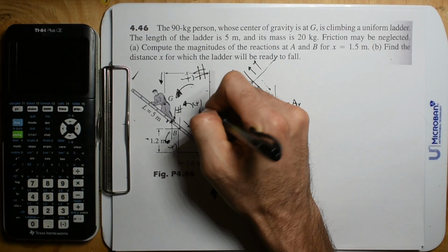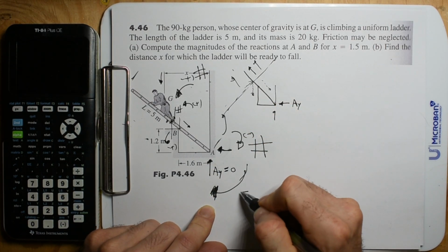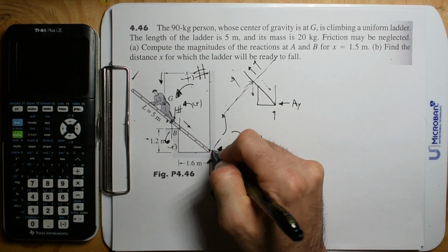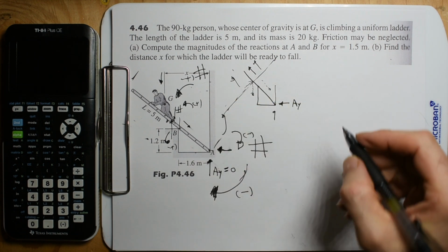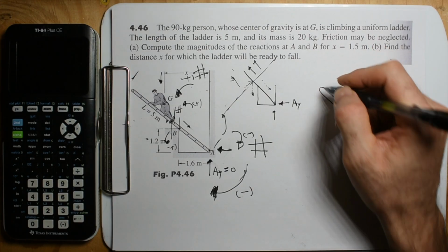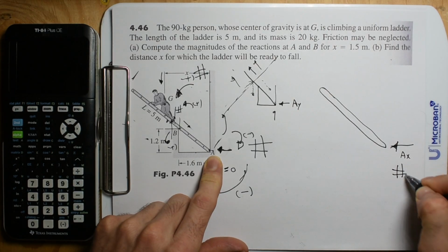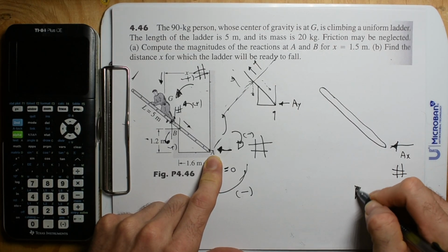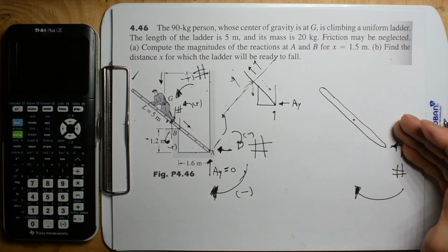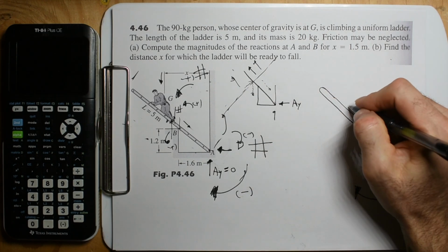So you have a small positive, a small positive. But here we just said that we're going to have a huge negative force, because in this scenario you have a lot of force up against this wall. And that is cool, because that literally goes back to the free body diagram of putting this thing in outer space. Like, hey, we're going to jam a huge force here. This AX is going to be quite large, and it's going to cause a huge rotating moment this way. So that has to be balanced. So let's just focus on this rotation, because these aren't going to help.